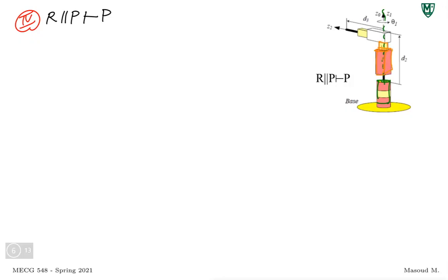And that is the axis. So they're parallel and on top of each other, obviously. And then the last one that you got is another prismatic joint, and this is its axis. So that prismatic joint and the prismatic joint before that, they're orthogonal. They're in the same plane. There isn't an intercept.